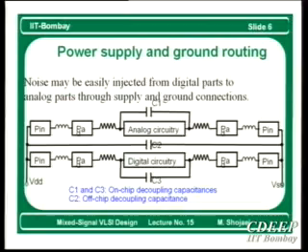But what is C1 and C3? So why do I need them? C1 and C3 are on chip, C2 is off chip. So this C2 plays a role of a low pass filter. In fact, if you include a small resistance of the wires on the board, then this will be like a low pass filter. So that is fine. But what are C1 and C3?